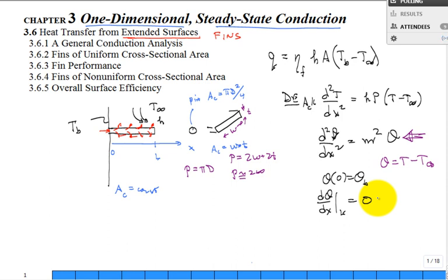All right. Well, we're going to then come out with an equation for this fin efficiency. And it's going to be the tan. Hey, tangent, my old friend. Nope, add an H. What is tanh? Hyperbolic tangent. That's maybe not my close personal friend. I know the tangent was. It's a little distant. You know, I haven't seen this cousin for a while. And it's going to be the hyperbolic tangent of mL. What is m again? A fin parameter, a fin coefficient.